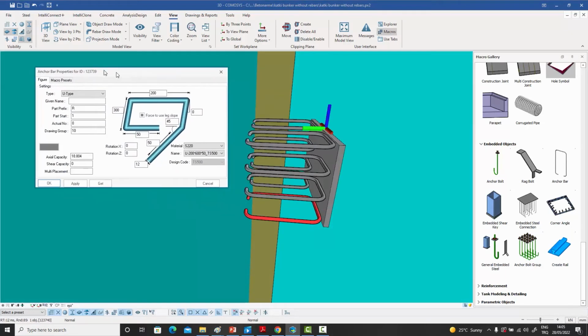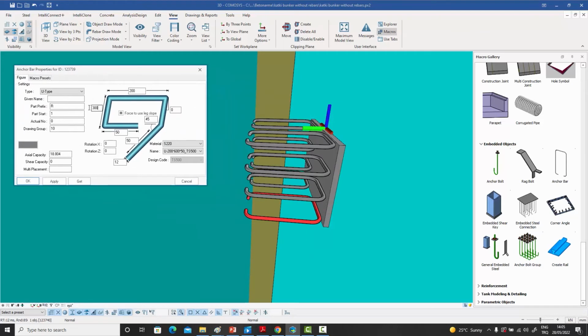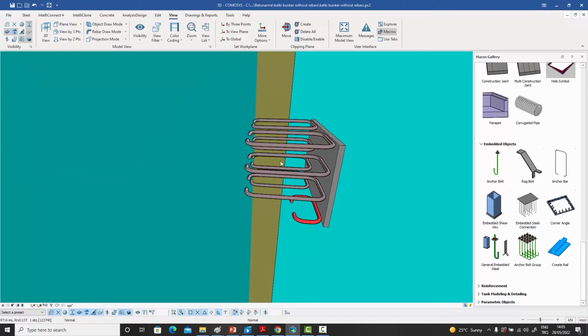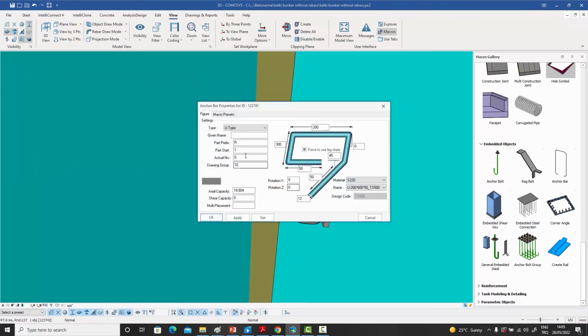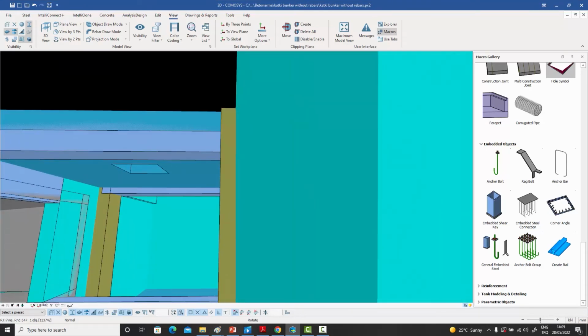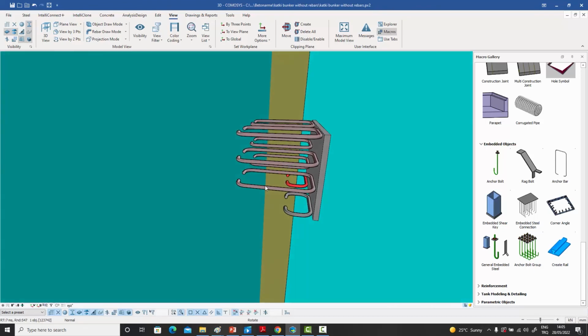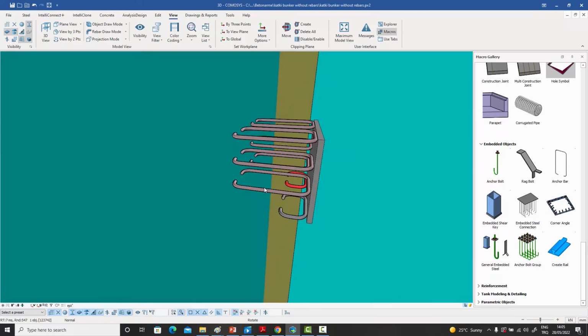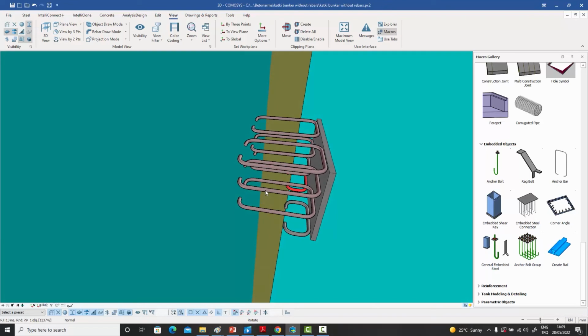So I can just double click on any particular bar and I say this particular one I want to be of a length of 100. And that particular one will be shorter. And maybe I can do the same to this one as well, or the top two. So I can modify exactly according to what my requirements are, even if the macro doesn't really allow that, because I have individual control over the embedded elements once the macro has been done with them.